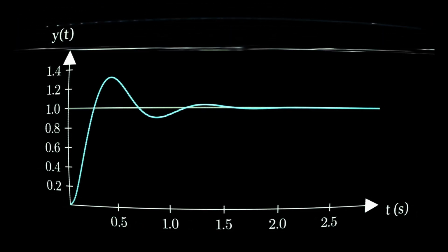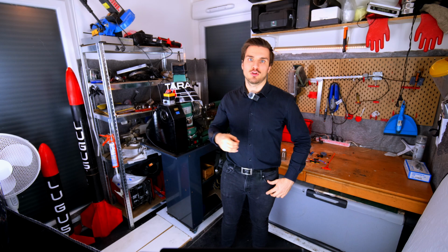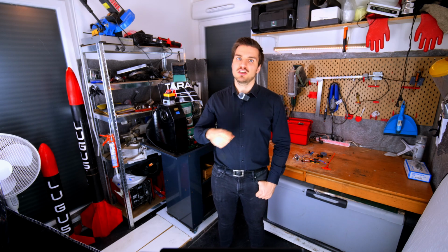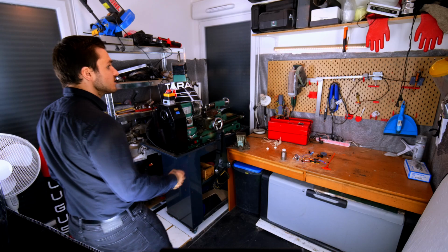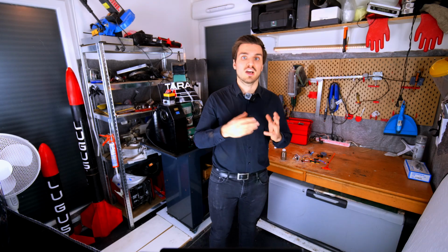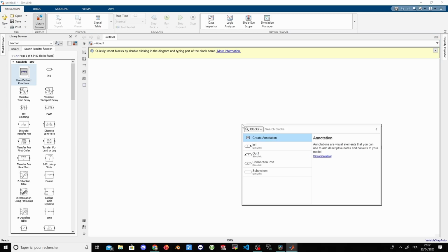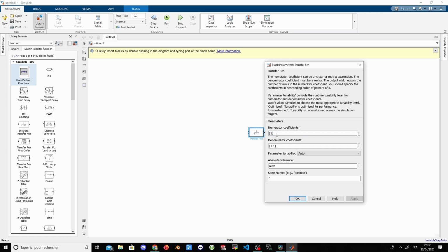Normally, a step response curve should look roughly like this. So once you have usable input data and a record of the command you used, you can generate the transfer function. Oh, and please don't forget to record the voltage of the battery. We will need it later. So now we know what's inside the black box. It contains a function we have obtained with MATLAB, and in Simulink, you can place a function block and write this function inside it if you want to simulate it.